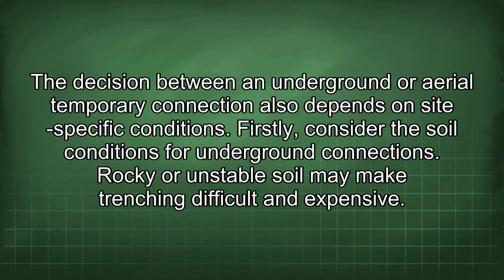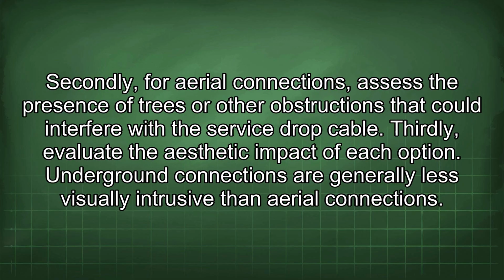The decision between an underground or aerial temporary connection also depends on site-specific conditions. Firstly, consider the soil conditions for underground connections. Rocky or unstable soil may make trenching difficult and expensive. Secondly, for aerial connections, assess the presence of trees or other obstructions that could interfere with the service drop cable.